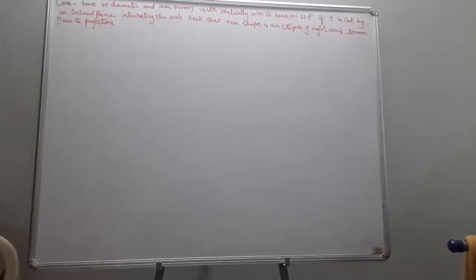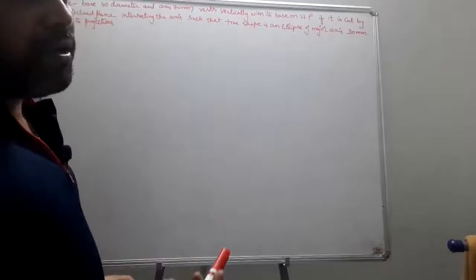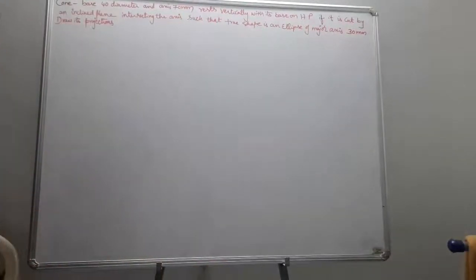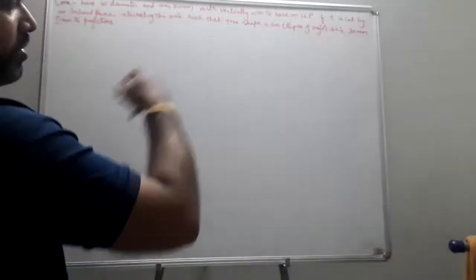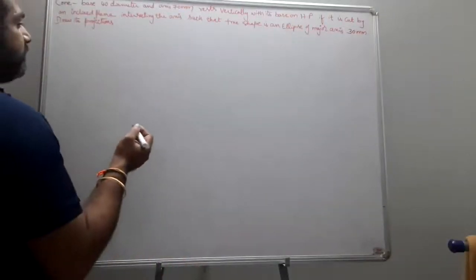So had you done this problem? This was similar to a trapezium, where the top view is going to be a trapezium. Here the top view is going to be an ellipse which already gives the major axis. So once we know this major axis, in the top view we just have the two endpoints, the major points, and we simply project the two endpoints on the two end generators. We will obtain the joining of those two. We will obtain the section plane. Let us see.